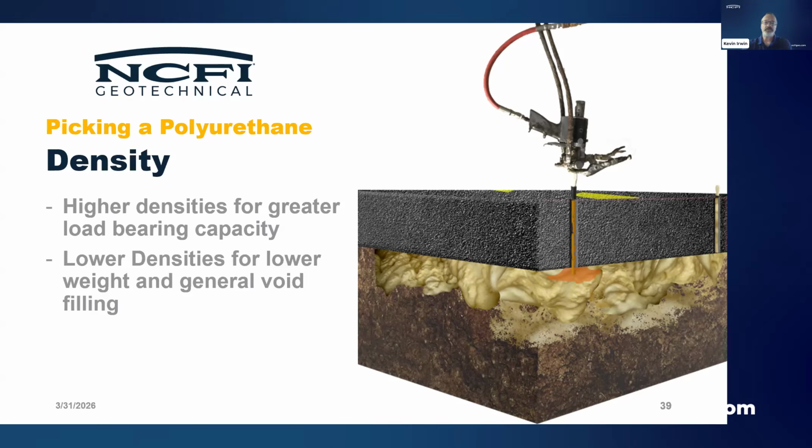But just know if you're using a 2-pound foam and you put it underneath something very heavy, that 2-pound foam will pack and could become a 3, 4, 5, 6-pound foam. I mean, it depends. It depends on how heavy it is, how confined it is, and if we can continue to still get foam in the ground.